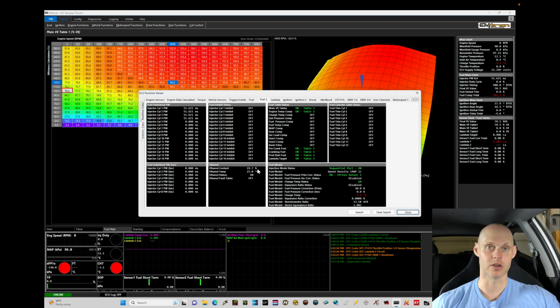And that seems about accurate because I've been using this car for filming on a variety of different standalone systems, doing flex fuel on each system, and I probably have a little bit of cross mixing between petrol fuel and the ethanol that's left as residual in the tank. So you should see, if you're going to be tuning on normal petrol fuel here in the United States, 8 to 10%. Worldwide, you might find you have ethanol-free petrol fuel, so it might be 0% ethanol content. Really depends on your location and what type of fuel blend you have already. But in this case, roughly 19-20% seems right for having a little bit of cross mix.